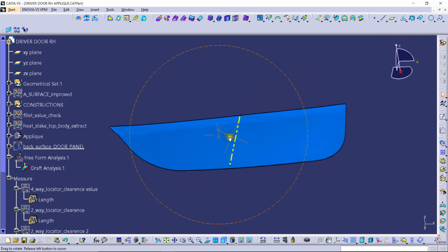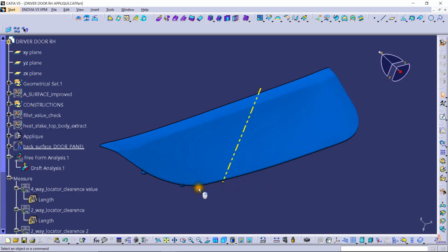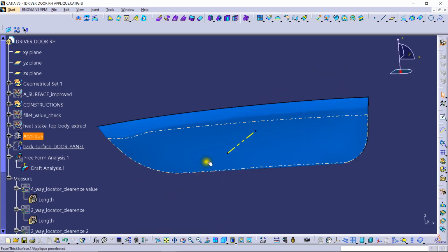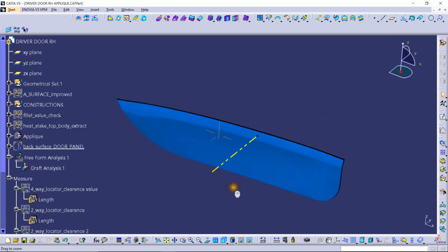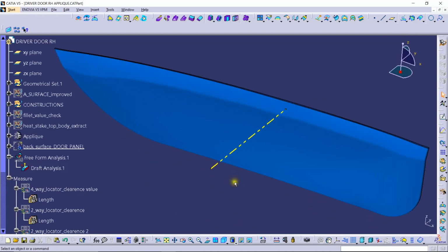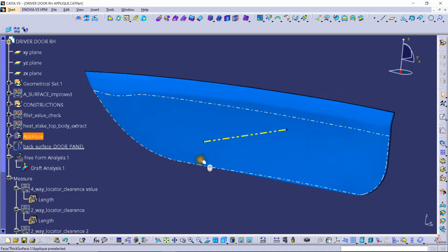And if there are any strength issues, they will create a detailed report and send it back to the NPD team, so they can create ribs or things like that to locally improve the strength and stiffness of the part. These are the four steps involved in the design process of any injection molded part, especially for automotive projects. They will cover all these steps to ensure the quality and safety of these kinds of parts.